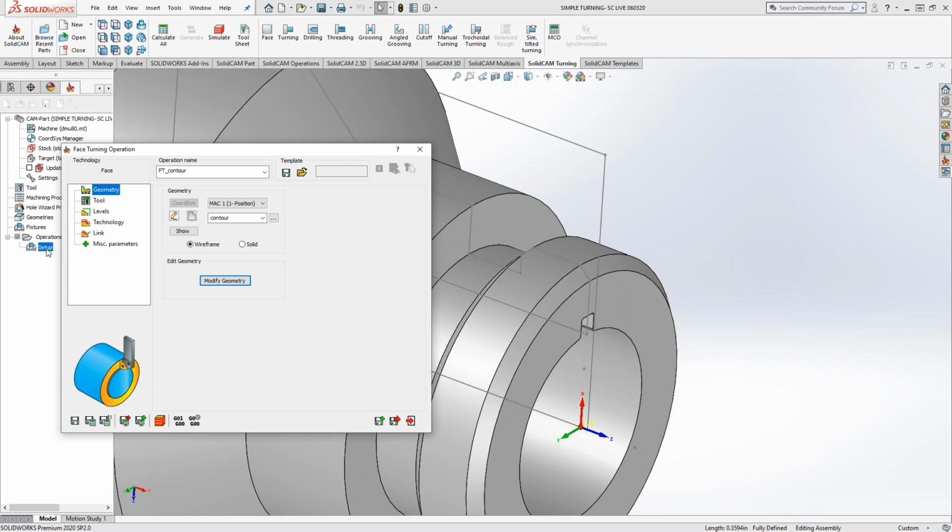So you'll find a lot in turning that your turn profile, your target profile gives you a chain that is not for the entire part, but there's auto extensions and there's ways to modify that so that you actually can turn a little bit more, maybe even account for corner radiuses in your inserts, that sort of thing.